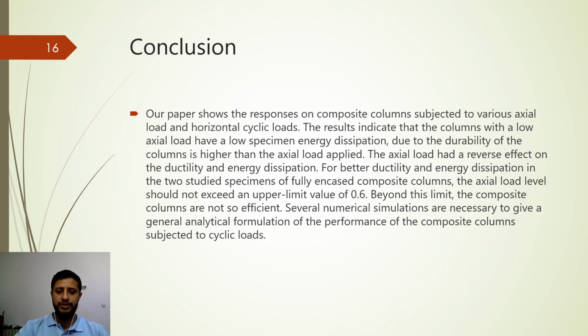Finally, the conclusion. Our paper shows the responses of composite columns subjected to various axial loads and horizontal cyclic loads. The results indicate that the columns with a low axial load have a low specimen energy dissipation, because the resistance of the columns is higher than the axial load applied. The axial load had a reverse effect on the ductility and energy dissipation.